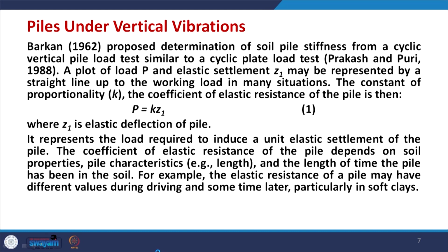Here one thing you need to understand is that for dynamic analysis, the pile is not a single element, rather it is a soil pile system. So, whenever we talk about stiffness, it is better to have the soil pile stiffness. What has been proposed is to determine the stiffness of the soil pile system using a cyclic plate load test, and then plot the load P against elastic settlement Z1, which may be represented by a straight line up to the working load in many situations.